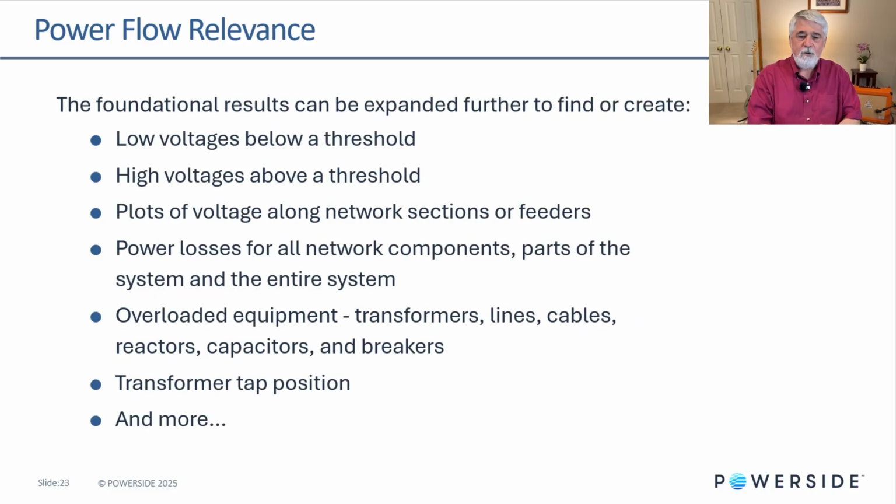Now, foundational results can be expanded even a bit further. We can find or create these commonly used reports in power flow solutions. These are the ones you'll find in everyone's solution. Low voltage conditions, high voltage conditions, in other words, below a threshold, above a threshold, anything above or below will trigger a message for you or be generated in a report as being over your threshold or under your threshold, plots of voltage along network sections or feeders, power losses.